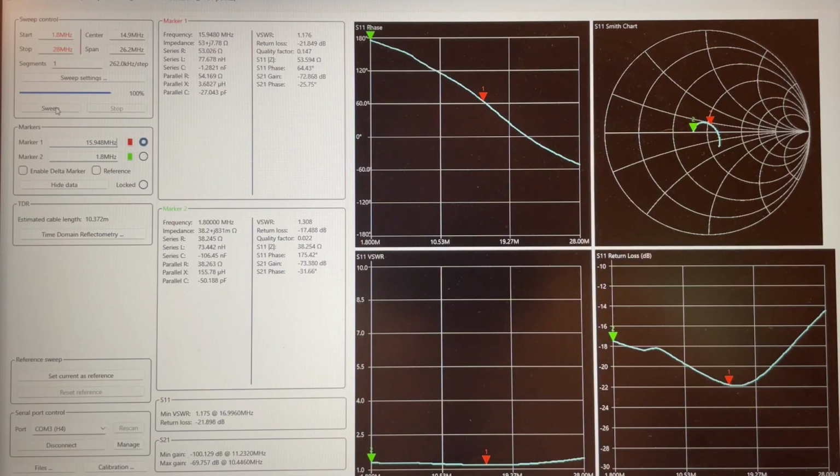I mentioned the Smith chart in many of my other presentations, but real quick, the top part of the chart is plus J, so that's inductive. The bottom part of the chart is minus J, so that's capacitive. The center of the chart is the non-reactive center or resistance. And at the very middle of the chart, here's our 50 ohms. So you see we have a nice tight circle around 50 ohms depending on the frequency.